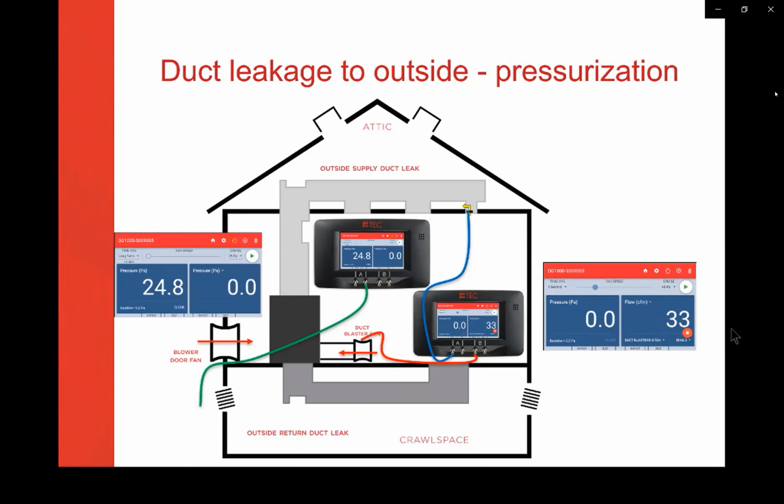You'll notice if you're doing a total leakage test, it'll show 4 dashed lines on channel B until you get above 5 pascals. So it's trying to convert the flow to what the flow would be at 25, and it can't do that unless the pressure is high enough. It certainly can't do it if the pressure is at 0.